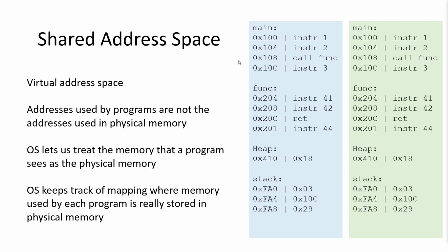But then there's a memory management unit that says, okay, this block of addresses right here actually appears somewhere else in the physical memory. It may be down in this space, somewhere in the 0x300s instead. So anyway, we're going to take a block of memory stored in physical memory, and all of these addresses get shifted to a real physical memory chip.